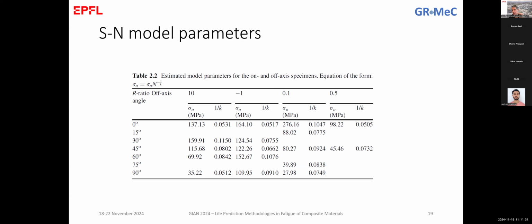And you can then attribute this frequency to the time that you spend, and you have exactly a creep test that is also correlated to your fatigue results. We'll see also later why the creep information for the material is important when we talk about fatigue.